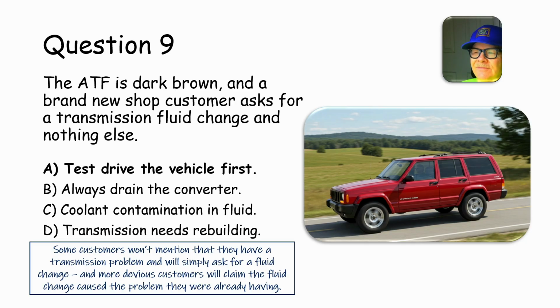Well, if you've been driving a long way on a transmission and there's varnish all over the valves, and then you put new fluid in there, sometimes it'll break that varnish loose, and it will cause the valves and the valve body to stick. You'll develop problems because you went too long without servicing it, and then you serviced it, and it washed off varnish that was really happy where it was, and those little varnish flakes will get in there and cause valves to stick.